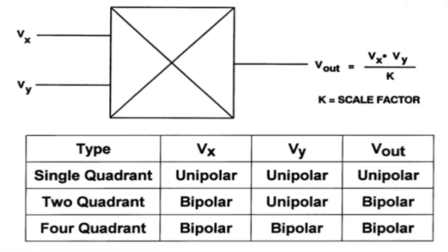However, they are limited to a signal of one polarity. If both signals must be unipolar, then we have a single quadrant multiplier, and the output will also be unipolar. If one of the signals is unipolar but the other may have either polarity, the multiplier is a two quadrant multiplier, and the output may have either polarity and is bipolar. The circuitry used to produce one and two quadrant multipliers may be simpler than that required for four quadrant multipliers. Since there are many applications where full four quadrant multiplication is not required, it is common to find accurate devices which work only in one or two quadrants.